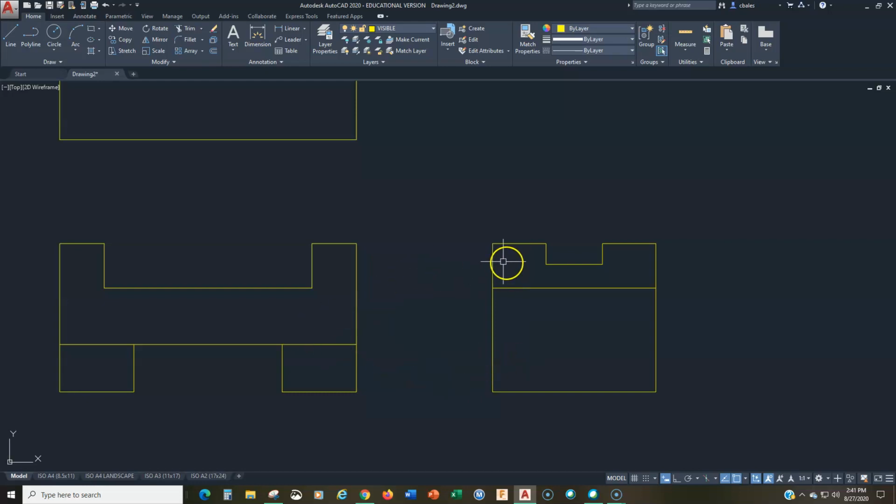That's a big issue. It's definitely a challenge sometimes. So I do suggest that you trim, clean up, erase, whatever, in stages, as you move along, not get all the lines in there and then try to make heads or tails out of what's going on and trimming. So, let's project this across and there, and then we'll offset. This is 7. And 15. And then we'll trim from here and get all this away.